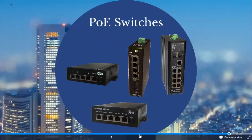Several different PoE switch options we have. We have passive and compliant, which is a PoE standard of 802.3 AF, AT, or now BT. Passive just means what you send through is what you're going to get out. And then the standard is there's a handshake to protect equipment. We have unmanaged and managed switch options. And then we have from a 3-port switch, a 4-port switch, 5 and 8-port with fiber output options as well. So our design team will, when we're doing that system design for you, if you don't have a switch in mind, be able to help make some recommendations as well.